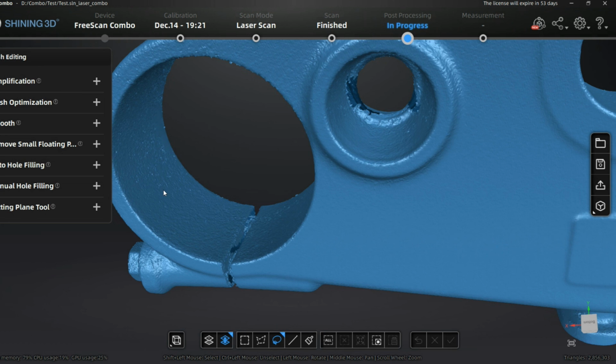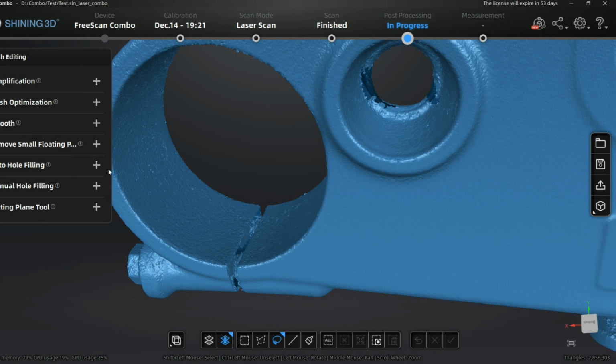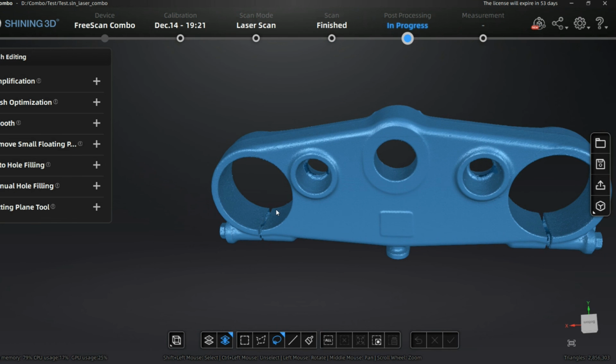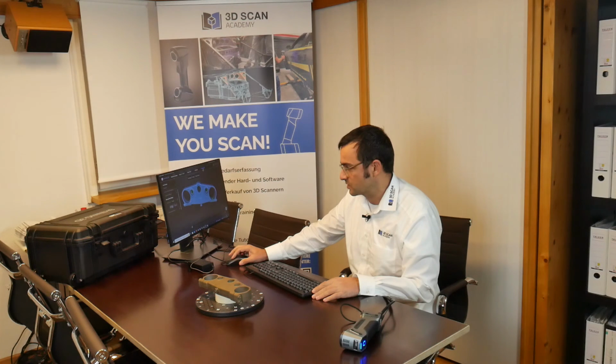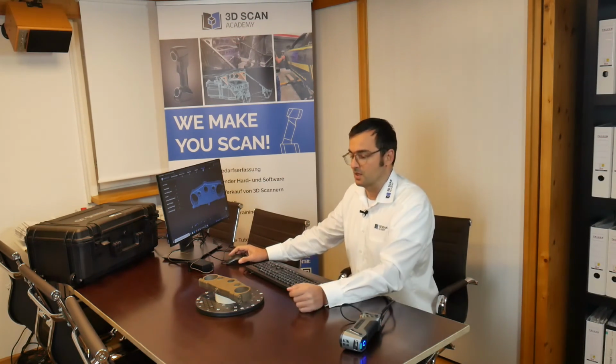Most of the times curvature based is very good, but it has the tendency of making a lot of bendings. Tangent is a good compromise, and just straight and flat filling is with flat that doesn't respect any curvature. Here you cannot even really recognize where it's filled very easily. If I would put the filter on here as well, the mesh would have been a bit more smooth, but overall it surprised me. It's a very good result, I guess.